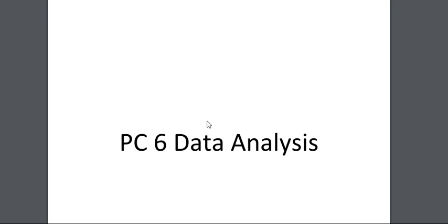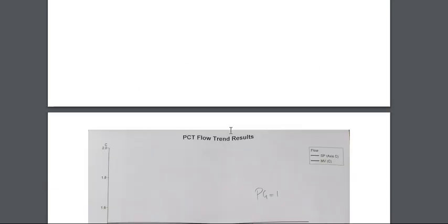The first one involves putting the system under proportional control, where we uncheck the integral and the derivative, and then we select a particular proportional gain. We select 1, 3, 5, 7, 11, like that, odd numbers.